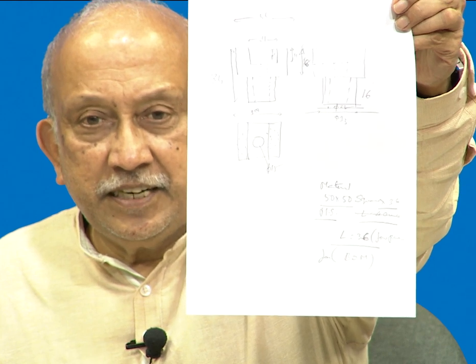This important right side bottom information is very important for bill of materials preparation. Sometimes the bill of materials is auto generated. If in my electric vehicle we have 4 jacks and 4 corners, then we require 4 of these bushes. The person who is preparing the process sheet and the person who is preparing the different types of orders for the stores will multiply all these things,